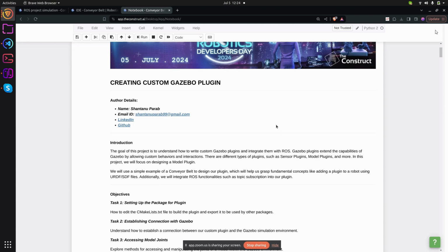We don't get something like a conveyor pulley joint, and we are limited to prismatic joints and other rotational joints. So what we do in such cases is we utilize something called plugins, that run in the background to make some changes in the simulation environment that will help us to get through the problem that we have.